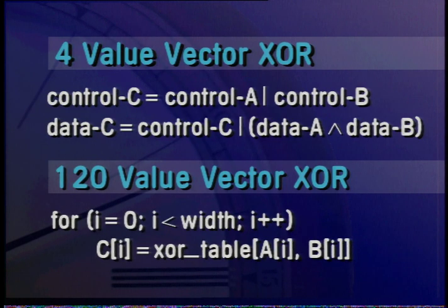By contrast, in the 120-value representation, each bit can have up to 120 different values. Thus, the vector must be split apart and the operation carried out in separate operations, one for each bit. This is basically an issue of scalar versus vector. If all models were scalar, that is, there were no aggregation of bits, then there really wouldn't be much difference due to representation. Since signal strength values can be represented in a byte, operations on them are always determined by table lookup. Different numbers of strengths simply result in different numbers of entries in the tables.